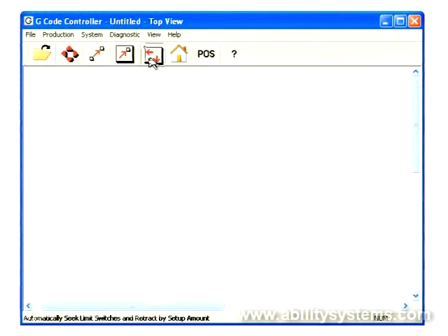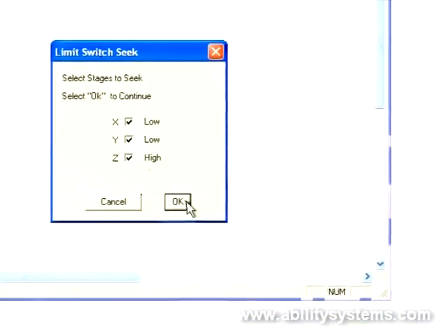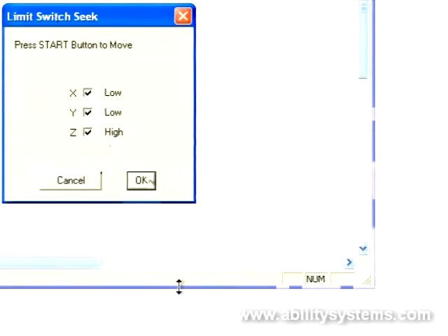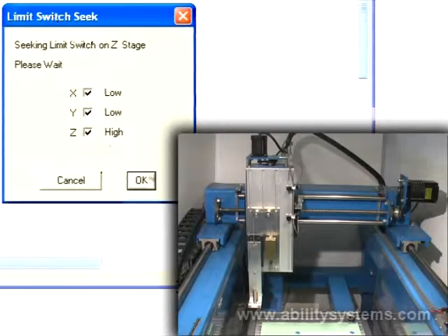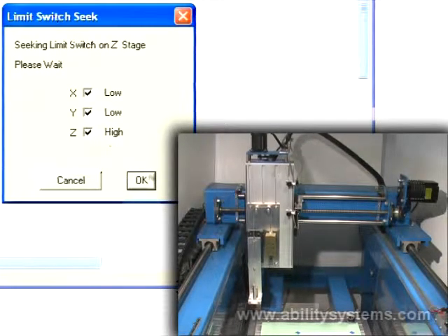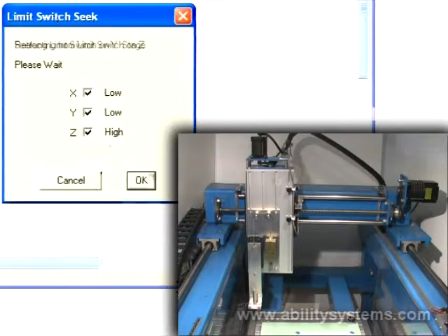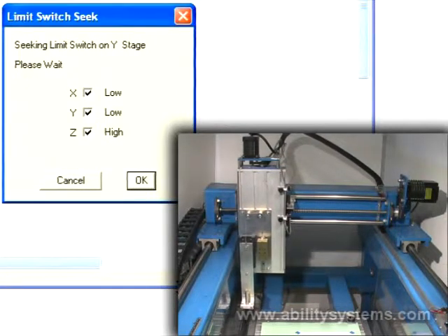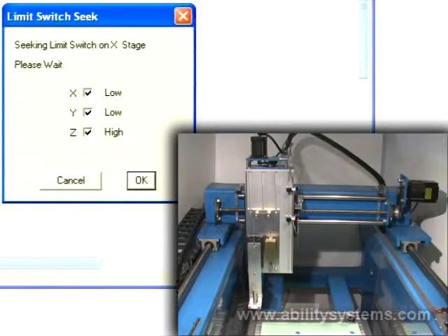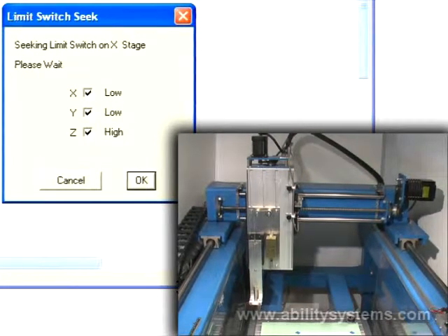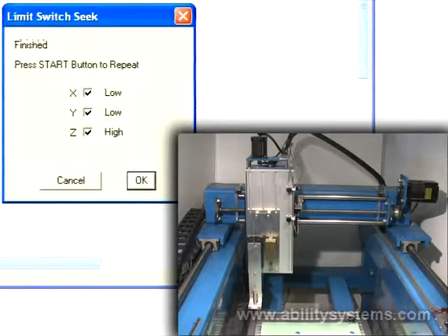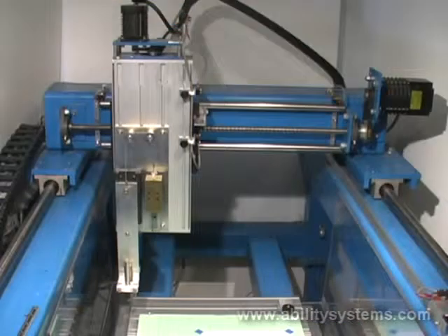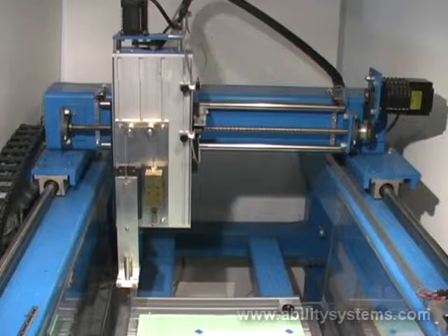In this example, the G-code controller application program directs Indexer LPT to automatically determine the home position. From an unknown position, it initiates an instantaneous movement lengthy enough to always be interrupted by an end limit switch. Indexer LPT reads the limit switch before sending each pulse, so the motor is stopped instantly when the limit switch is contacted.